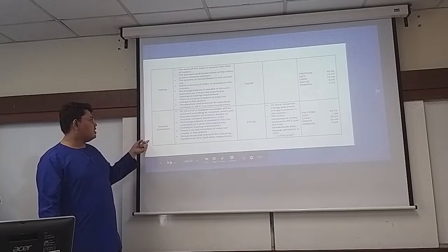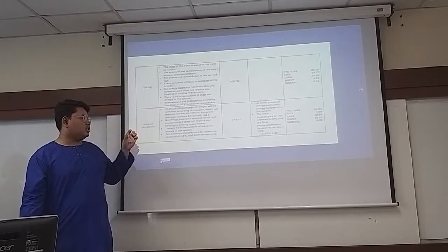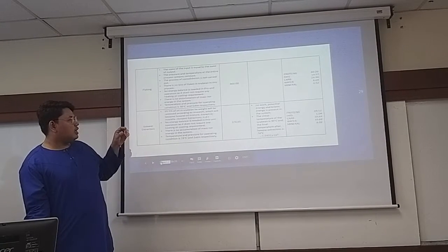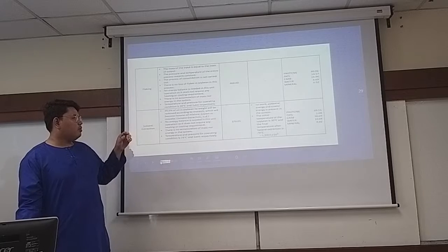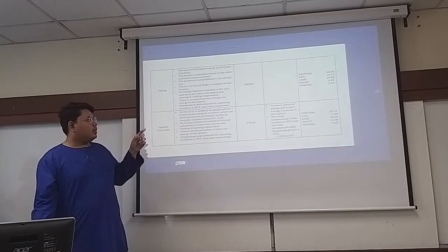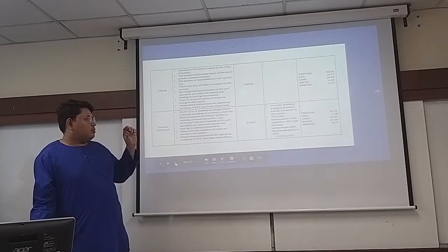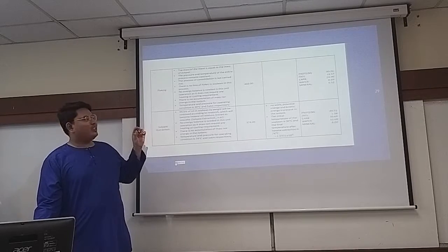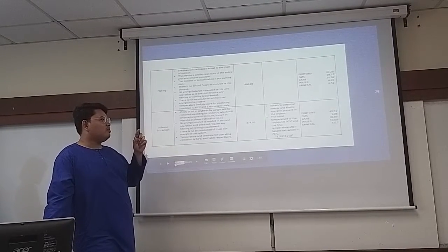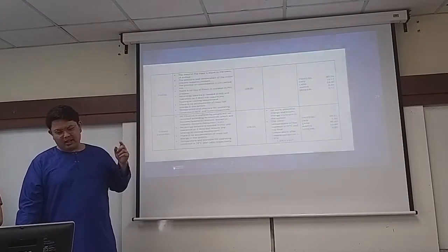Next is solvent extraction. So the overall mass balance is 374.05 kilogram per hour. And there is an energy balance, which is negative 1.5931 to the power of 9 joule. Then the composition is protein 49.54%, fat 1.08%, carbohydrate 30.69%, water 10.69%, and mineral 8.02%.